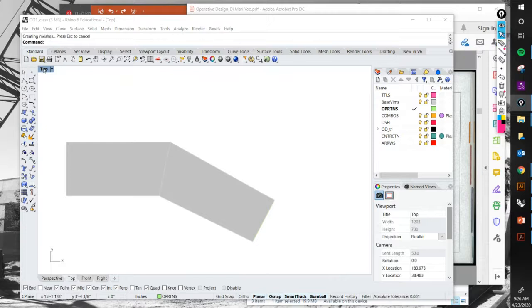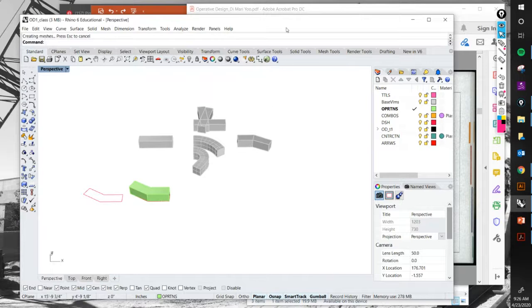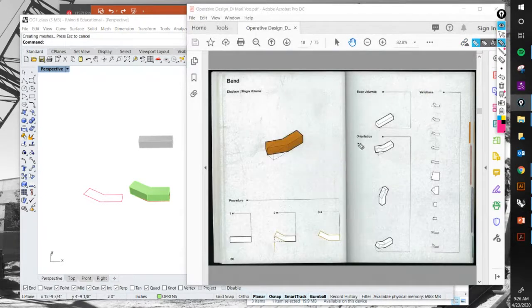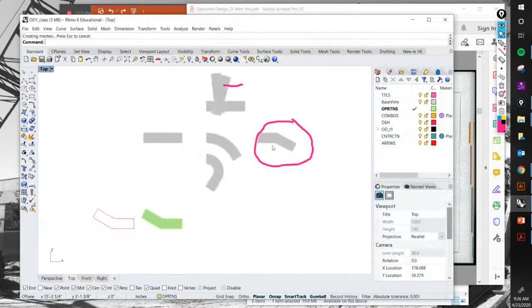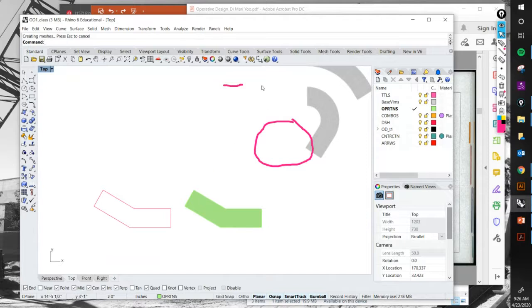So that for me would be an example of bad modeling technique, right? A bad judgment. Because if what we're after is just the form itself, the formal interpretation of the bend action, not the bend command, the bend action, I would argue that this could be achieved in a much more precise way by starting in 2D, or a top view, drawing it from there and extruding it from there, right? That would be my take. I could also see other takes on that.